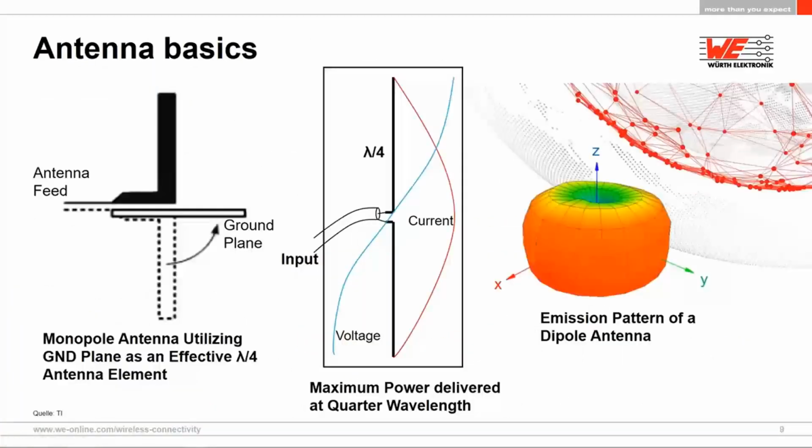How do we actually get this information out into free space as a radio signal? And for that, invariably, we need an antenna. Now, the antenna is a conductor, copper or aluminium, something suitable for conducting, fed through a coax cable or directly off the driver module.